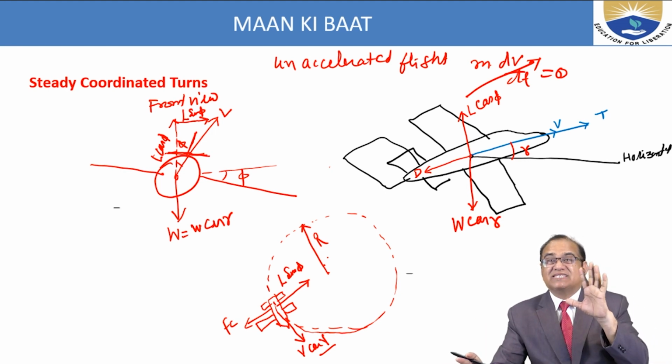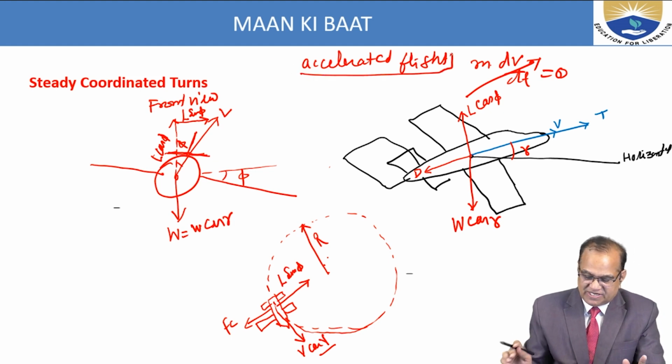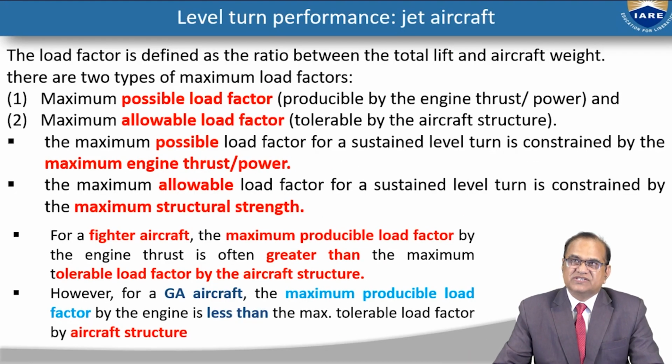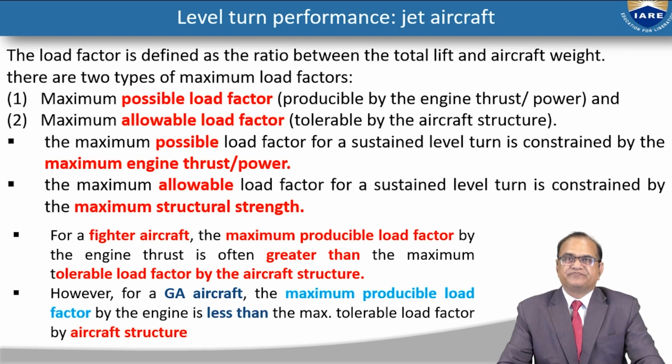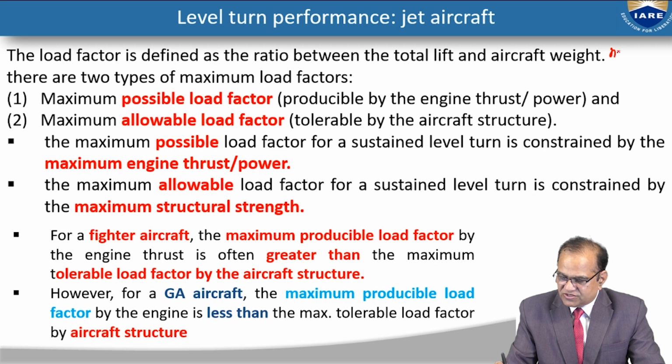So turn is an accelerated flight, as it is mentioned here. Now I will go for the further discussion of level turn performance for the jet aircraft. The load factor is defined as the ratio between the total lift and aircraft weight. So load factor n is equal to L by W.